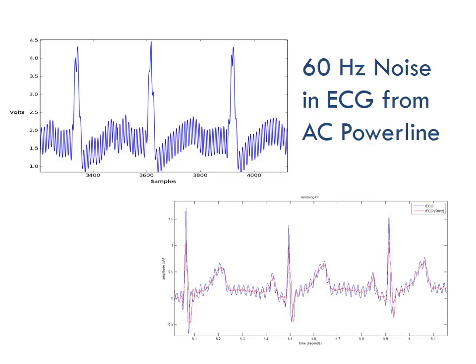In the bottom right-hand corner, again, the blue is your input. If you remove the 60 hertz signal from that blue signal, you get left with that red signal, which is a much, much cleaner version, and we can do better math with that, and we can actually look at and analyze it much better from a physiological standpoint. So a doctor can see problems that are happening, where if you give them the signal in the top left, it's much harder for your eye to identify what's happening there. This can be especially important in things like tachycardia.